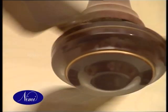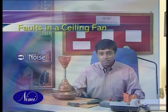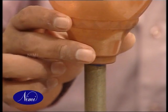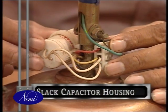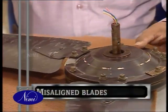Carelessness in handling will cause the blades to wobble, which will end up in noisy operation and also shorten the life of the fan. The faults that generally arise in a ceiling fan are noise, low speed, jamming of the rotor, and not rotating. The cause of the noise could be slack canopy, a worn-out grommet, loose or missing screws, a slack capacitor housing, dirty or worn-out bearing, misalignment of blades. A humming noise might arise due to non-uniform air gap owing to the displacement of the rotor.